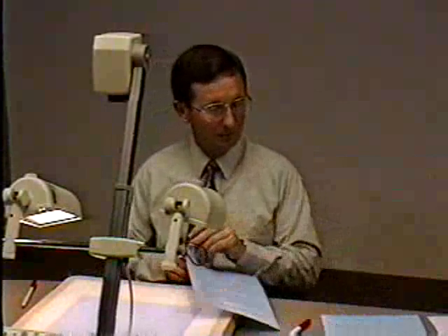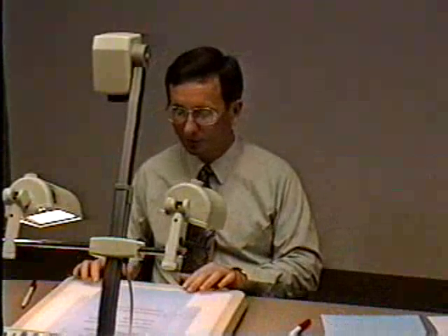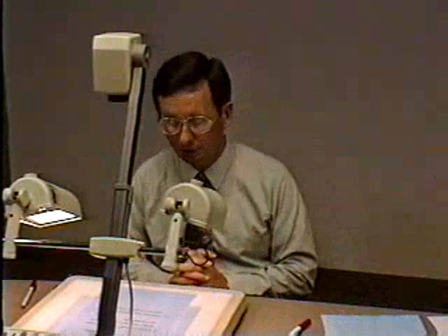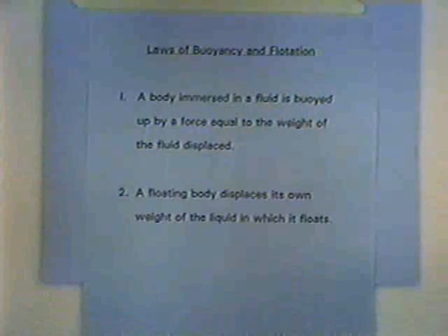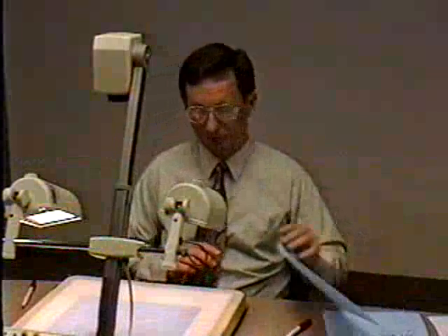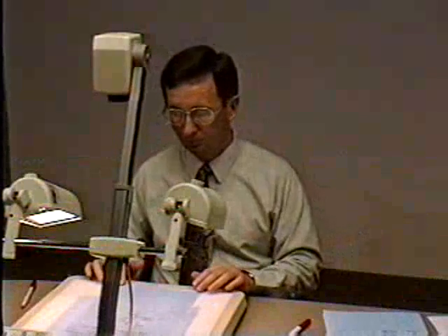Now the third problem will illustrate the concepts of buoyancy and flotation. And the basic concepts are summarized here. First of all, a body immersed in a fluid is buoyed up by a force equal to the weight of the fluid displaced. And secondly, a floating body displaces its own weight of the liquid in which it floats. And so we can illustrate that by this example.